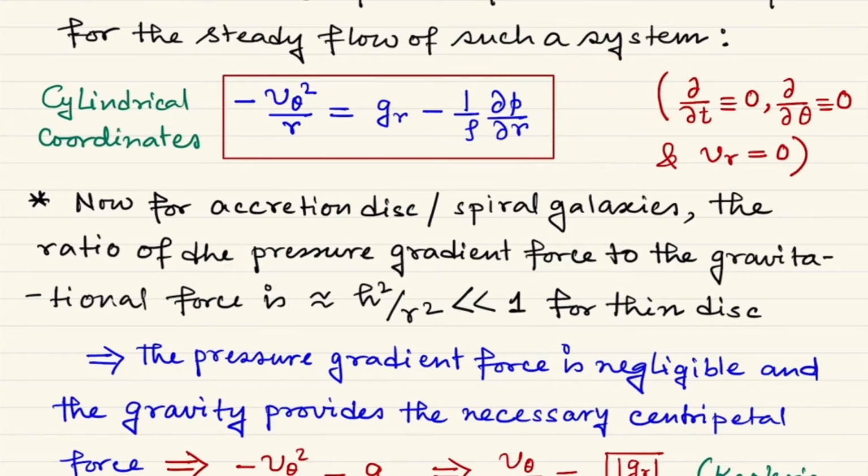And that's exactly the case where we are neglecting the viscosity, at least for this rotation purpose. That means the contribution of viscosity to counterbalance the net centrifugal force, or to provide the necessary centripetal force, whatever, they are equivalent pictures, is negligible.